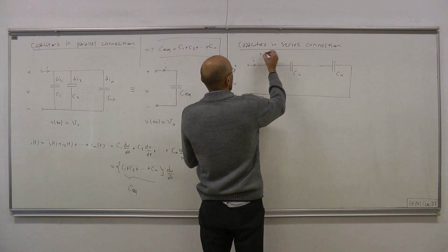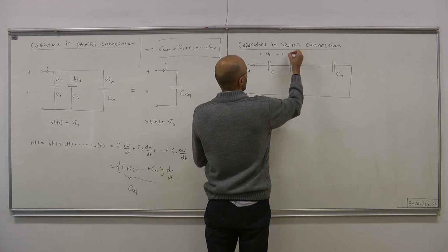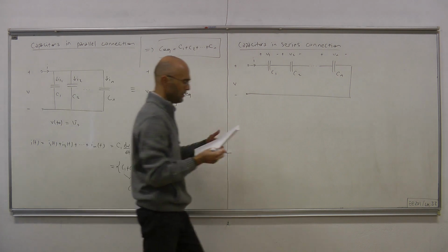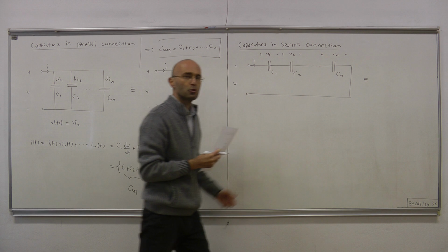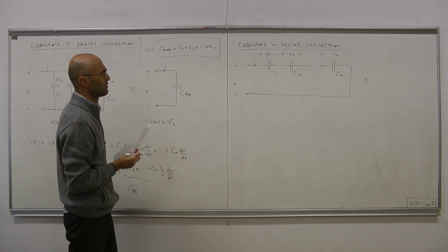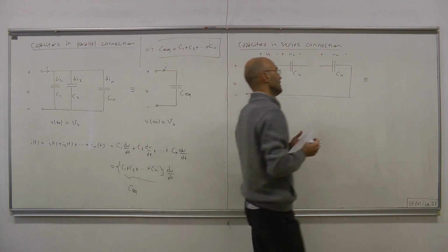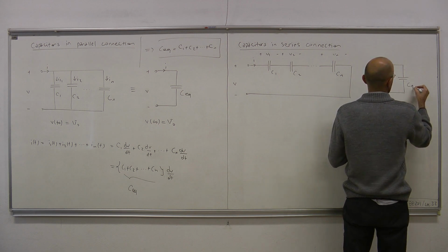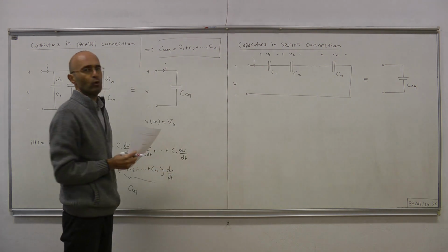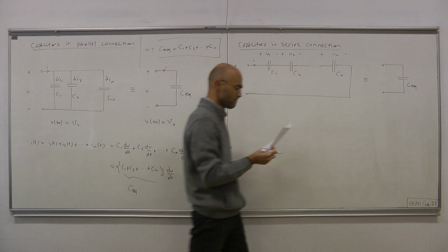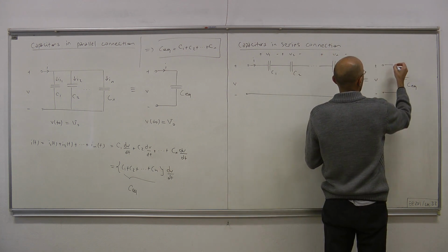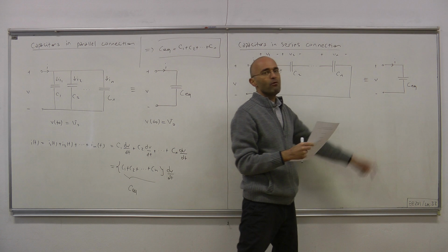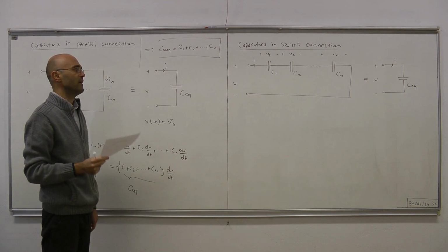Okay. So let's label the voltages. This is V1. This is V2, and this is Vn. Okay, and we will now investigate if it's possible to represent those n capacitors by a single capacitor, where the capacitance to be figured out we call C equivalent, or sometimes it's called C effective. Okay. And by definition of equivalence, this one port and this one port are required to have the same voltage and current readings at all times, provided that they are connected to the same circuit.